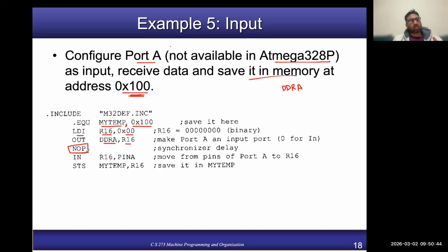Why? Because it takes some time for the ports to settle. Before you configured it in the input mode, on the physical pins there is some garbage or random values, and we want to get rid of that.